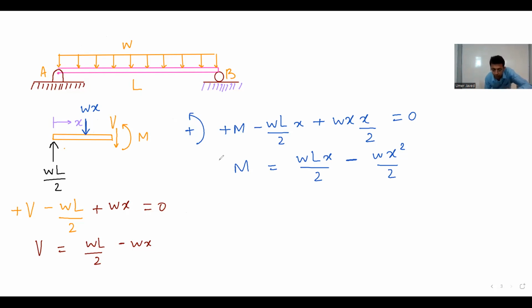No? Okay. Now, if you have the moment, why don't you write that equation? What was that equation? Anyone who can please open the notes? M is equal to EI d square V over dx square. And what is V, by the way? V is the deflection of the beam. I'm repeating intentionally, so everyone understands that V is the deflection of the beam.